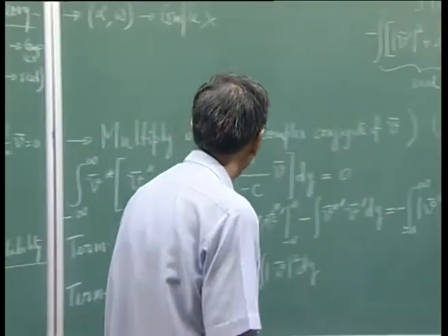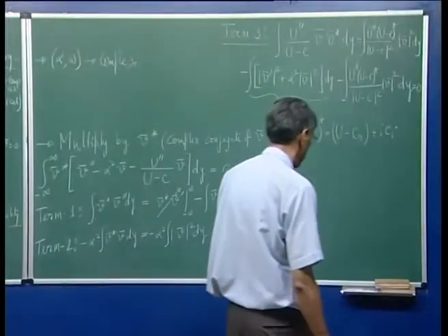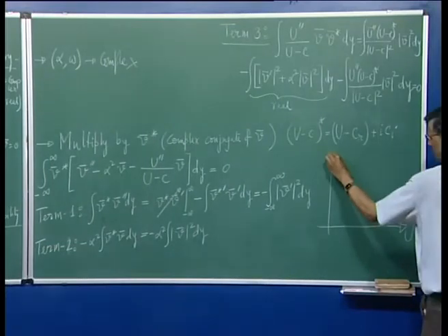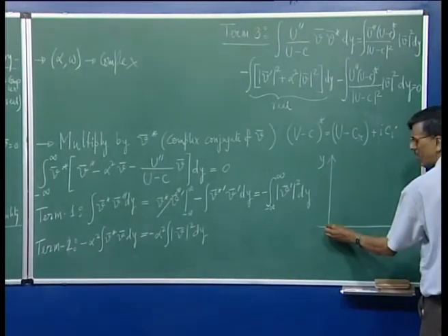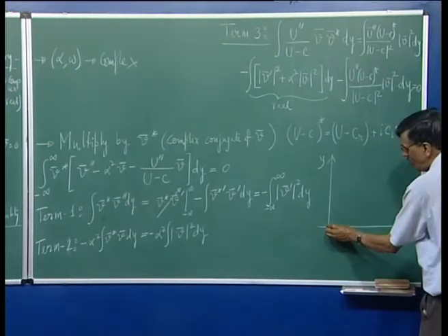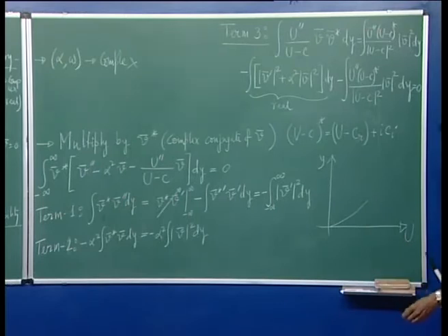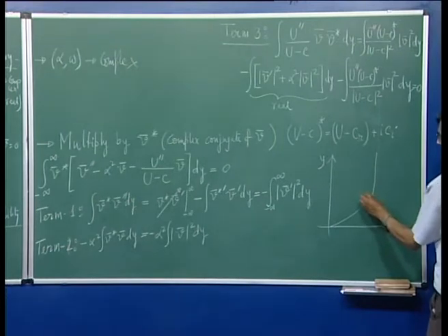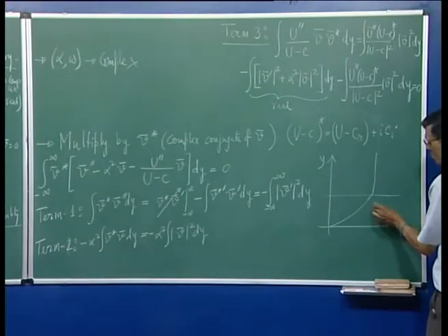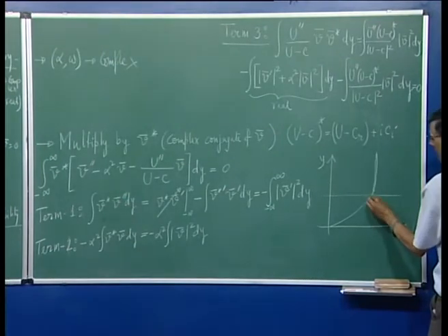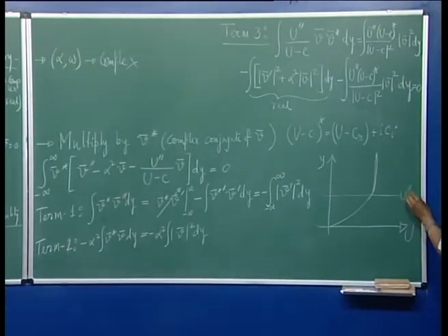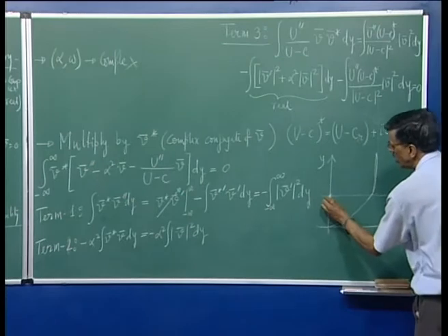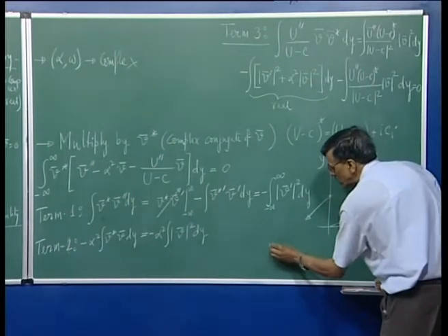So if I am talking about a velocity profile which we sketched before, I would have a velocity profile where it will have, let us say, a positive value, then it will have a 0 value somewhere. Okay. So there would be a place where I will have u double prime equal to 0. So this point is called the inflection point.